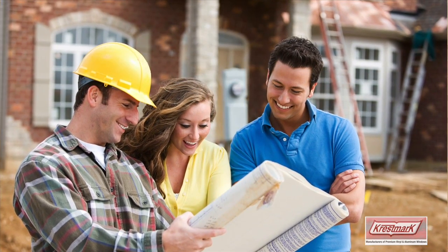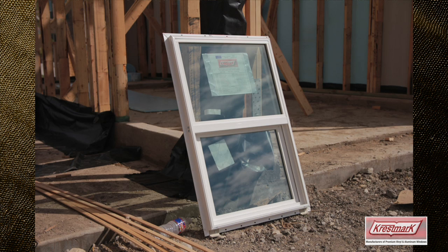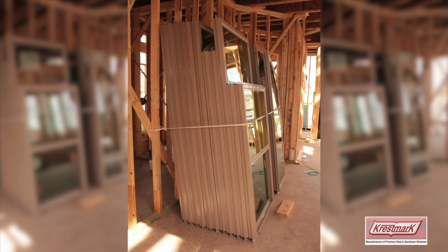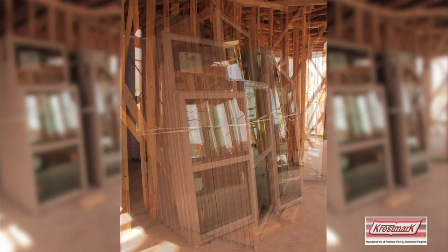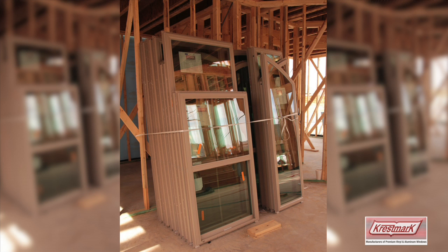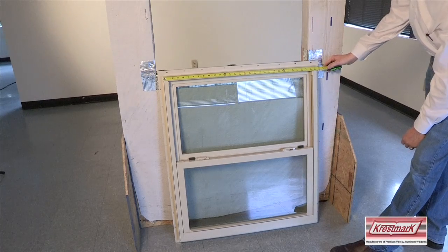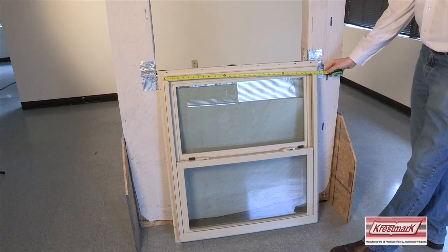When installing a Krestmark window, the installer contractor has a few key responsibilities to keep in mind prior to installation. Do not store a Krestmark window in direct sunlight or with loose windows stacked on top of each other. The windows should be secured upright and in a shaded area prior to installation. Check all local building codes for window and installation requirements. Check the window for obvious damage. Check that the window ordered is correct as far as size, grid pattern, color, and operation.